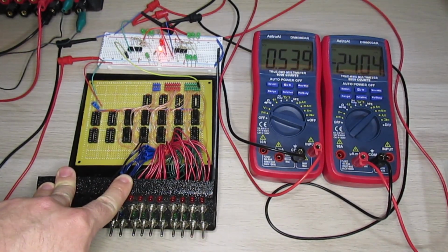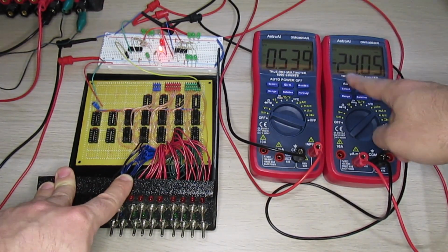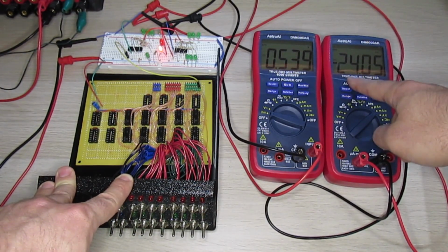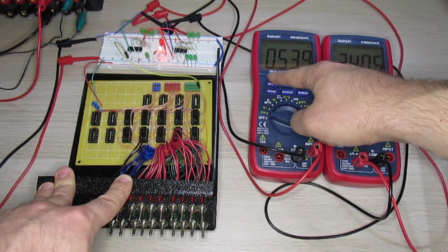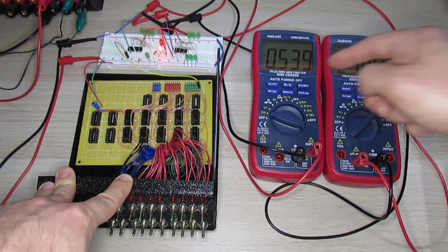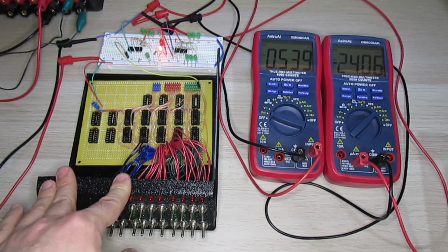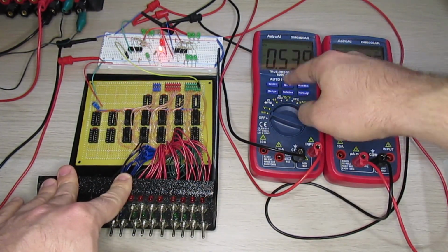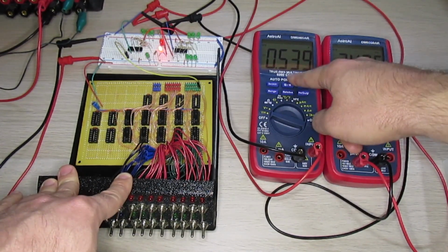Seeing the output low state, we're now drawing 24 milliamps, which is way outside the 16 milliamps that the datasheet asks for. And you can see the output low voltage has gone up above half a volt now, 0.54-ish volts, which is outside of what the datasheet promises of 0.4 volts. But again, since the inputs will accept up to 0.8 volts, we still have enough wiggle room and everything seems to work fine.